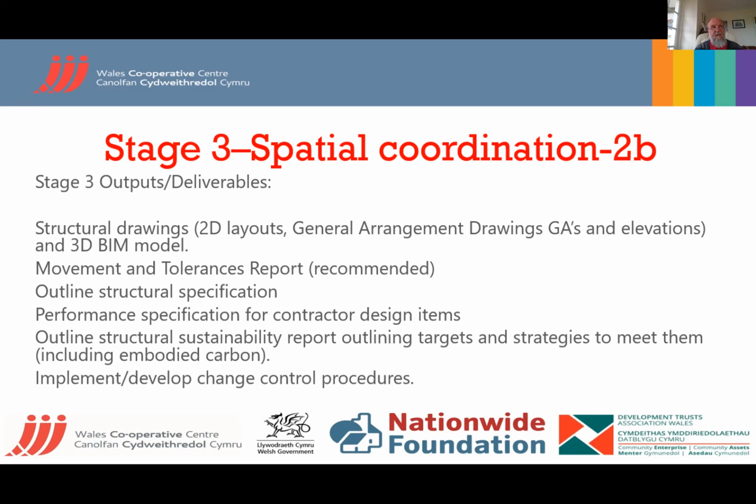particularly if you're going for air tightness. In an old British standard for bricks, 24 bricks have to be a certain length, and there's a tolerance of 6 inches with a brick over 24 bricks, because they vary in size because of the firing process. It averages out in numbers. They're normally 9 inches or 215 millimeters. That's their average size, and it does work out. But there's tolerance of things.